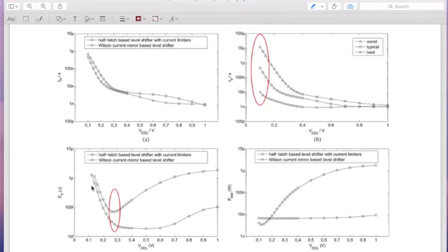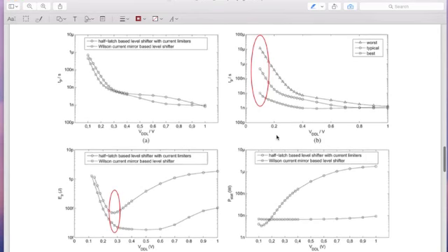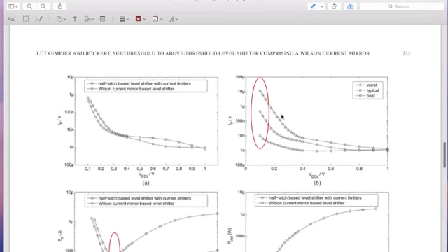That's because things become so slow at these very low voltages that you're dominated by the leakage energy. And this is something we'll see again and again with minimizing energy, where there's an optimum voltage at which energy is minimum.